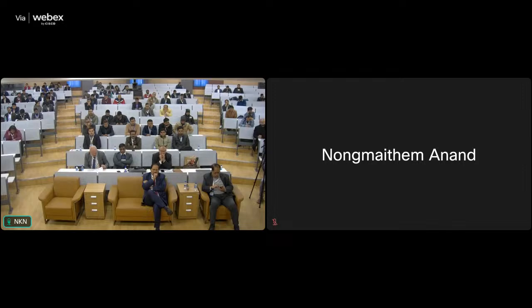But when we consider the improvement in Q because of the grouting, you will see it will increase from 1 to 3, right? So it will move to the red dot. The same size, same ESR value, the shotcrete thickness will go down to 50 millimeter, 5 centimeter.